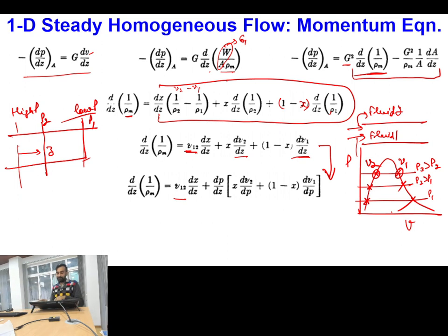So that's why whatever values of V1 and V2 we are considering, those V1 and V2 are changing along the length. Basically, these are thermodynamic properties which are changing. Particularly whenever I am considering the liquid-gas combination, I am operating within the liquid vapor dome, and within the liquid vapor dome, variation of property is dependent upon any single independent intensive property.